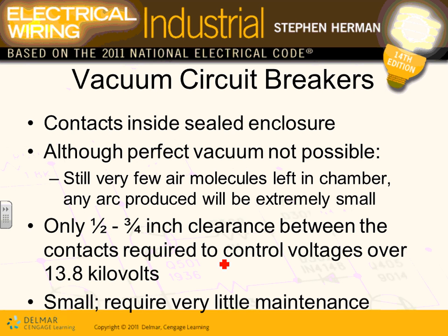They have a tube like this. They have a process of removing the air from the tube. And inside it, they have contacts that they open and close. So when you open and close with no air inside, you have no arc or a very, very limited amount of arc. That's it. If you have no arc, guys, then you can make the circuit breaker interrupt the circuit and live to fight another life.